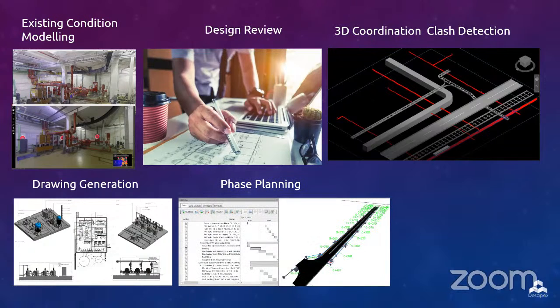The next use case is phase planning, or we generally call it the 4D modeling. Because BIM can capture phased information throughout a facility's lifespan, it is ideally suited for communicating long-term how a project may be constructed, occupied, maintained, and eventually renovated for reuse. Using BIM allows us to graphically communicate the sequence of renovations in both time and required actions, so that everyone has an understanding of how various people and departments will be impacted during each phase.